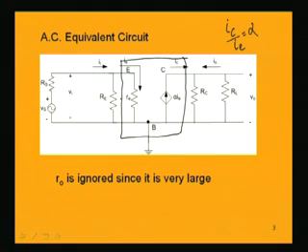That is why IC can be assumed to be a dependent current source whose value is alpha times IE. That is why we write alpha times IE in the dependent current source. The direction of current for this PNP transistor is this; it goes out of the device, and the input current IE comes into the device. So, this is the AC equivalent circuit.